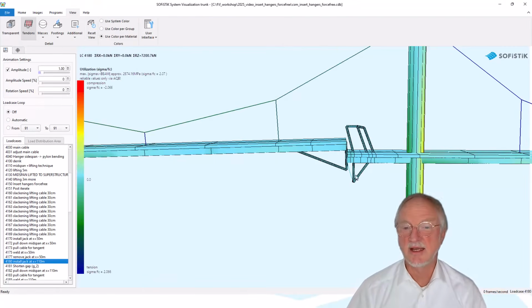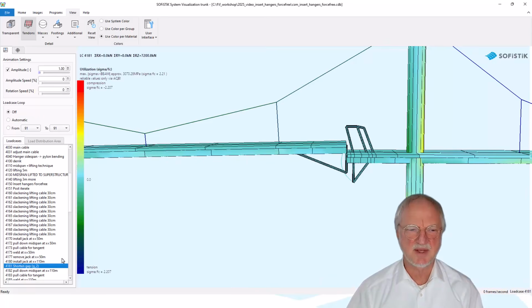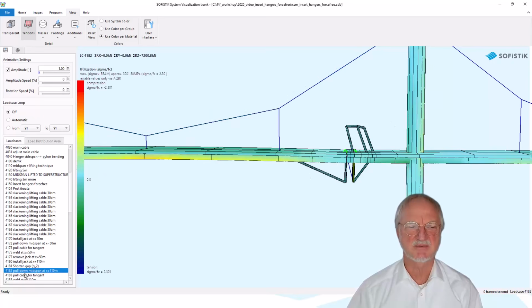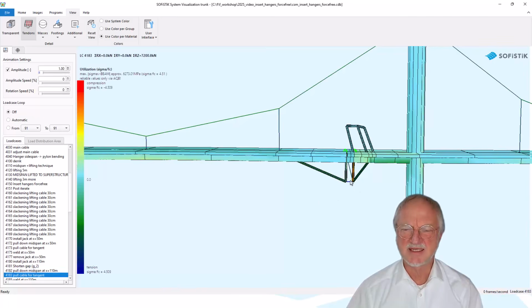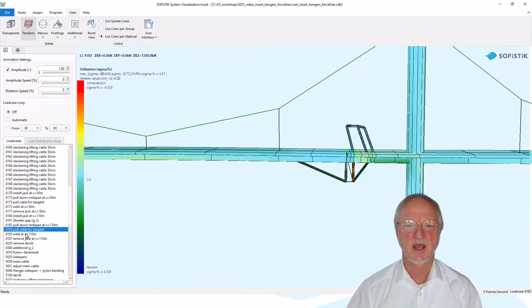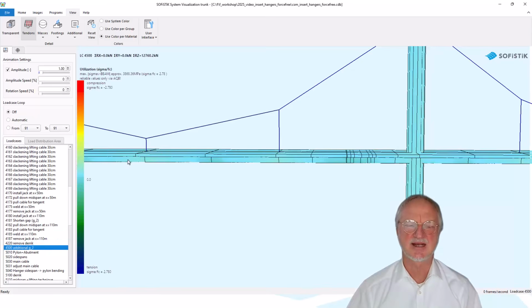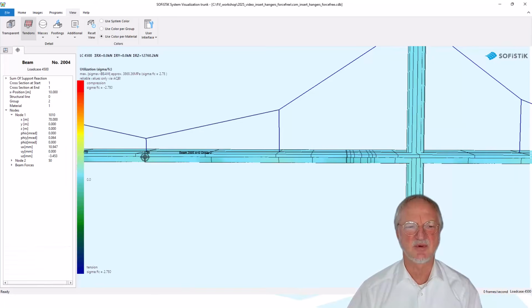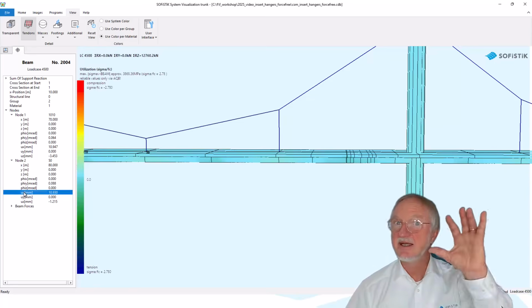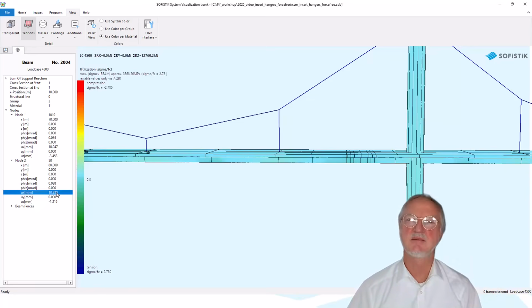We install an additional mechanism on the right side. We shorten the gap a little bit, we pull down the midspan. Now we pull down this cable to get the correct tangent of our bridge. And then we can weld it together. Then we can remove the direct. And now we can activate the additional dead load. And when we now activated the additional dead load, I click here to this point, number 50, we can really see our deformation is nearly 0, only 10 millimeters.